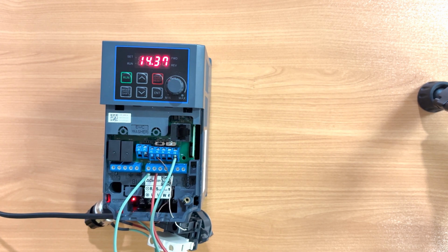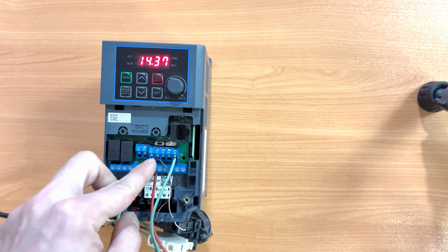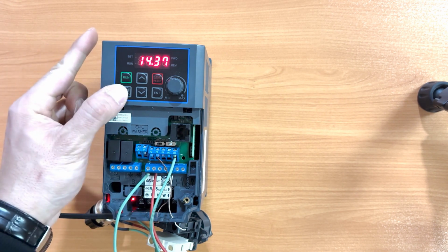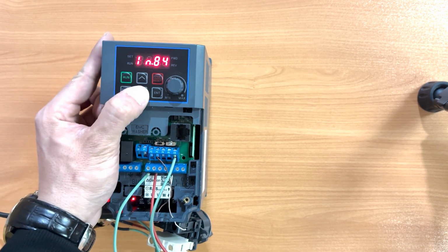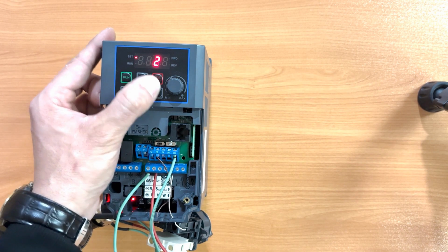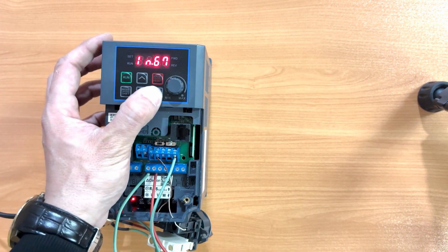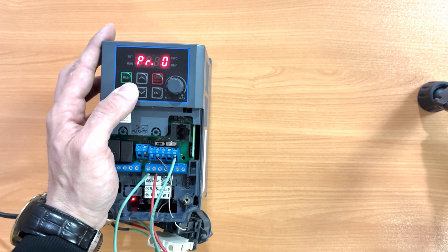So, as we said, in order to activate the analog hold feature on the G100 inverter, we need to set one of our digital inputs, whichever we choose, to the value 21. Here, I want to use the digital input P3. I go to parameter number 67 in the group, which is related to the P3 digital input, and set it to the value 21. Now my P3 digital input is defined as analog hold.